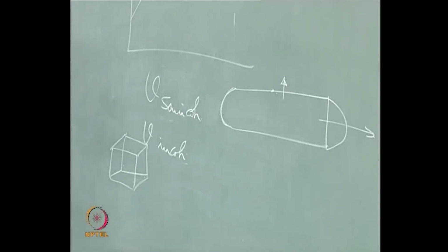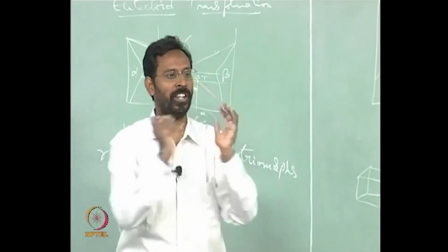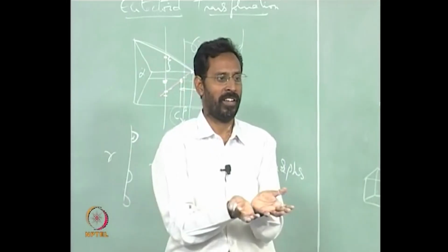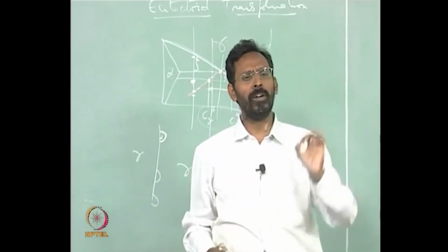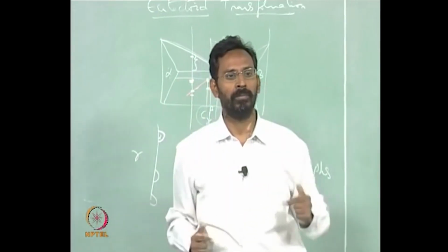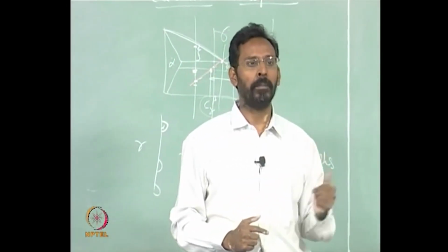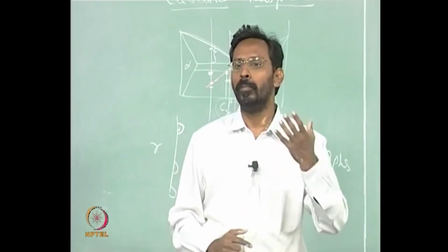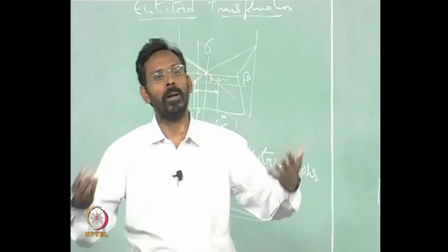Each plane here, if I consider, we have talked about Wulff's plot, that there is a shape for the nucleus. Once I consider there is a shape for the nucleus, there are so many planes which are covering that nucleus. Out of all these planes, whichever plane needs fewer atoms per unit area for it to grow, that will be the one which grows faster. That means the loose packed planes will grow faster than the close packed planes. Close packed planes need more atoms.